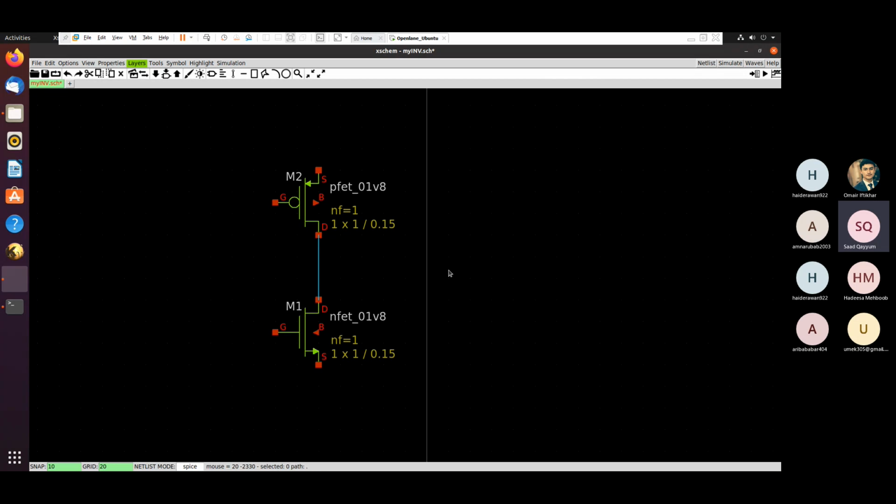It is finished. Similarly, if I want to connect the gates, I move to the gate, press W, move, and click. It stops. Then I want to move down again, so I bring the cursor here, press W, move down to the point where I want to stop. And again, I left click, it stops. Then again, I want to start from here, W.